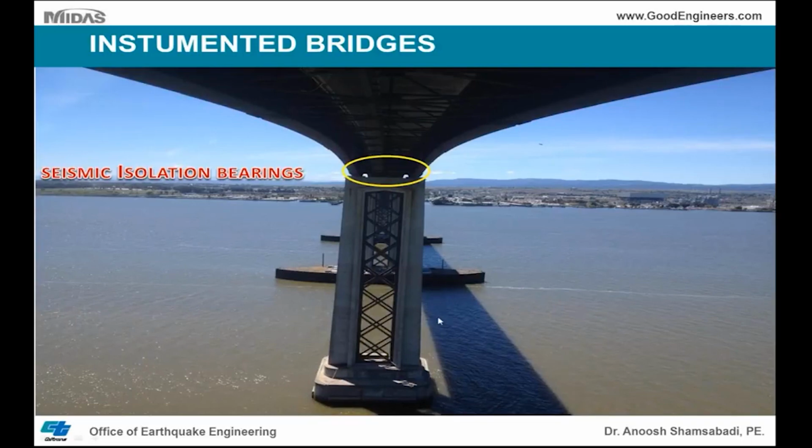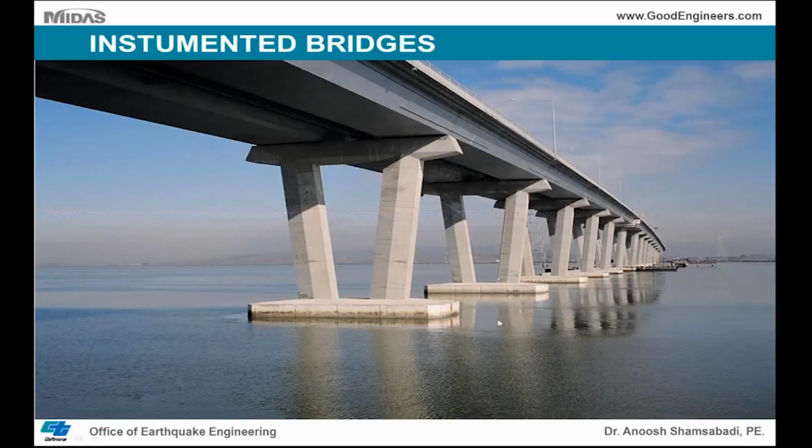Now, as you can see from this photo, the pile caps are very massive. Therefore, you have to include them in your structural model. Here is another example of an instrumented bridge. You can see again, the pile caps are very massive, and therefore they need to be included as part of your foundation and superstructure model. And that's why we need to use computer programs such as Midas and other computer programs that have the capability of doing a direct model, which means including the piles, pile caps, and superstructure within the model. And I will explain it as we go further along.